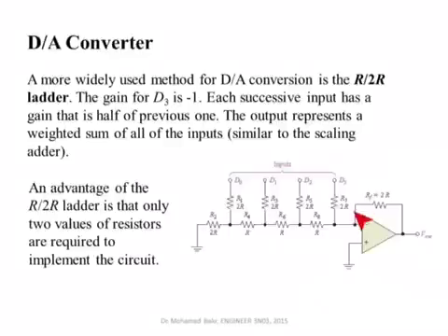The gain of this circuit, as I will show you, is simply an inverting amplifier, but the weights of these resistors, the 2R, 2R, and R, are adjusted to guarantee a certain input resistance value, and a certain Thevenin value for each one of these voltages.